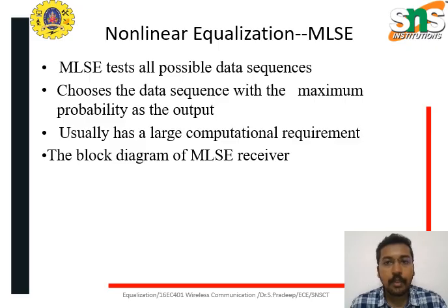Nonlinear equalizer, particularly using maximum likelihood sequence estimation, is a technique employed to mitigate distortions in communication channels, especially those with severe amplitude distortion or deep spectral nulls where linear equalization struggles. MLSE, as a form of nonlinear equalization, focuses on finding the most probable sequence of transmitted symbols given the received signal, thus addressing distortions that linear methods cannot fully resolve.